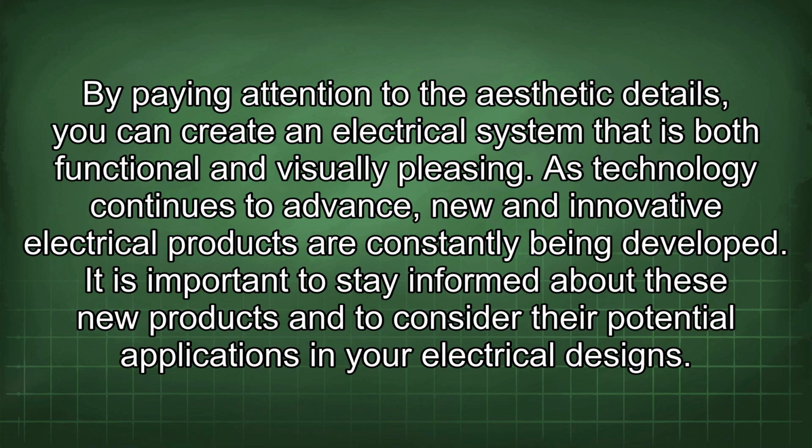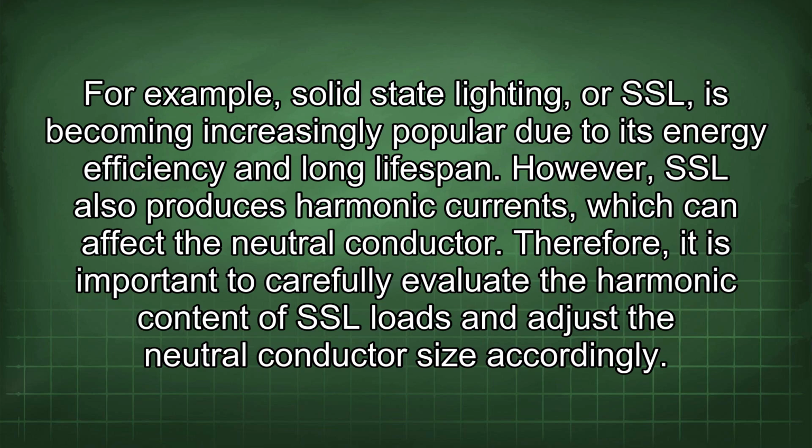As technology continues to advance, new and innovative electrical products are constantly being developed. It is important to stay informed about these new products and to consider their potential applications in your electrical designs. For example, solid-state lighting, or SSL, is becoming increasingly popular due to its energy efficiency and long lifespan. However, SSL also produces harmonic currents, which could affect the neutral conductor. Therefore, it is important to carefully evaluate the harmonic content of SSL loads and adjust the neutral conductor size accordingly.